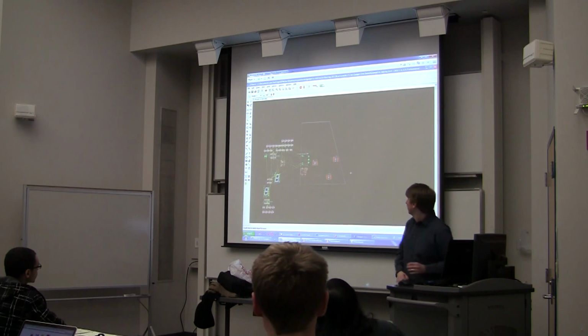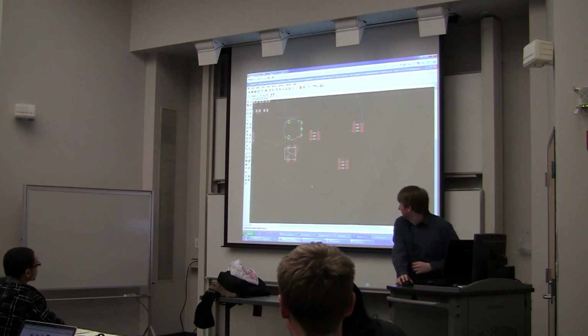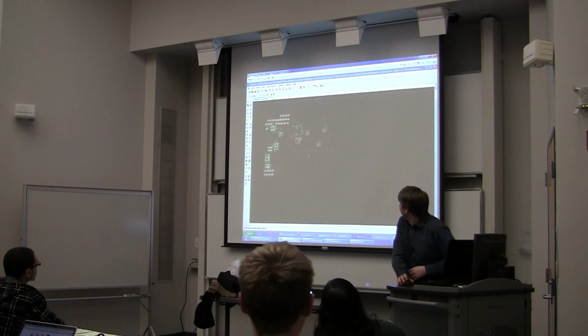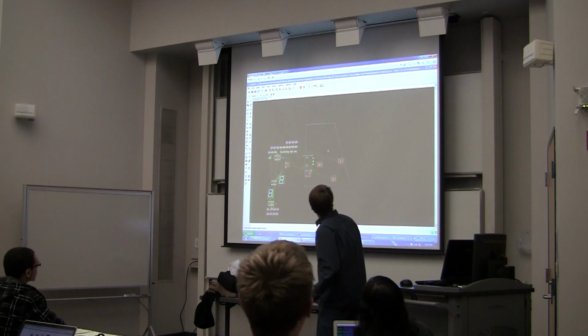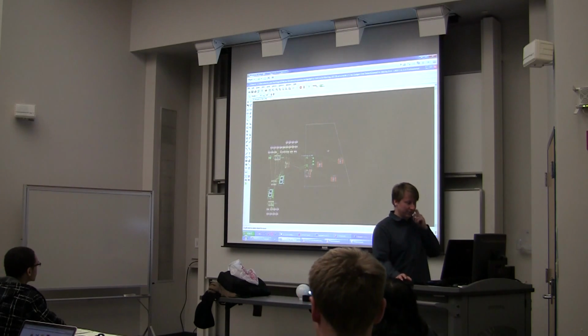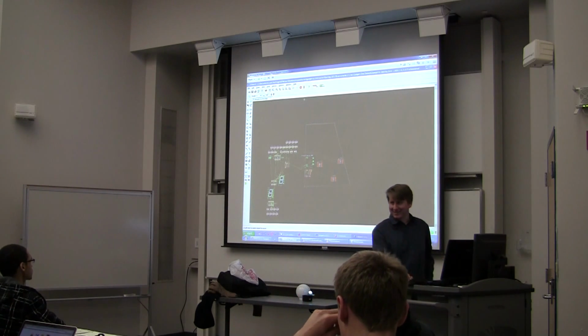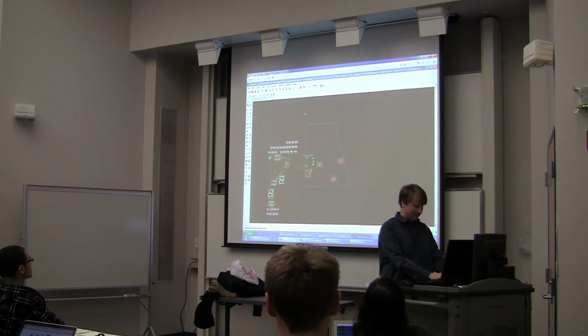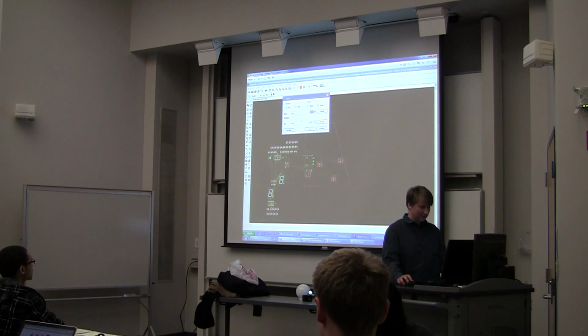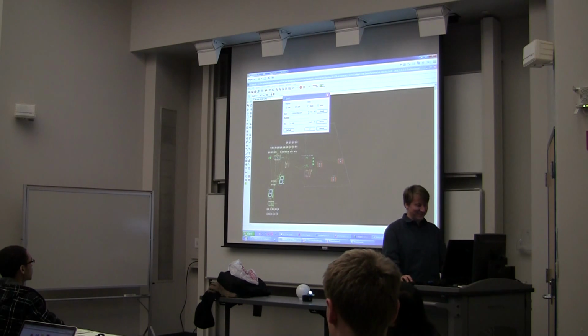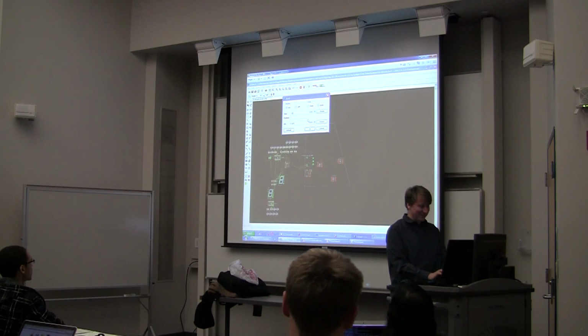Can you not see the lines? The projection is not showing my grid lines. But if you type grid on, it'll show you a grid. Just type grid with no parameters, and you get a dialog box. Here you can set things, and you can also set display on or off. I think the finest might set the thickness of the lines. Oh no, that did something wrong. Don't use that finest. I'm going to go back to quarter inch.